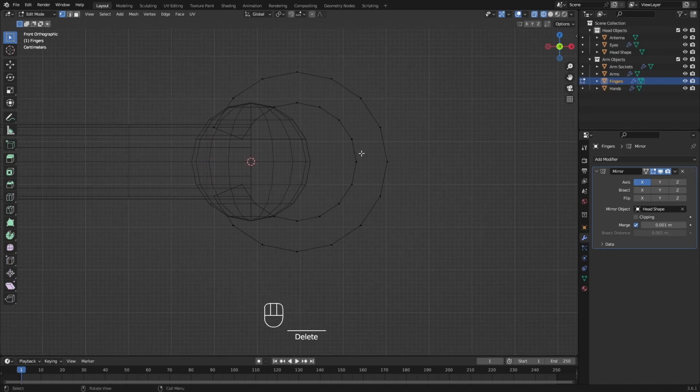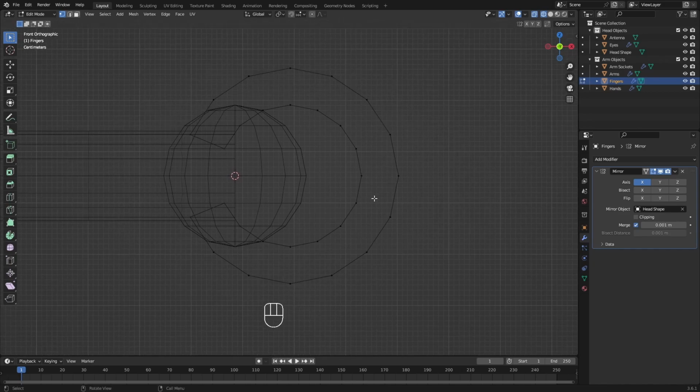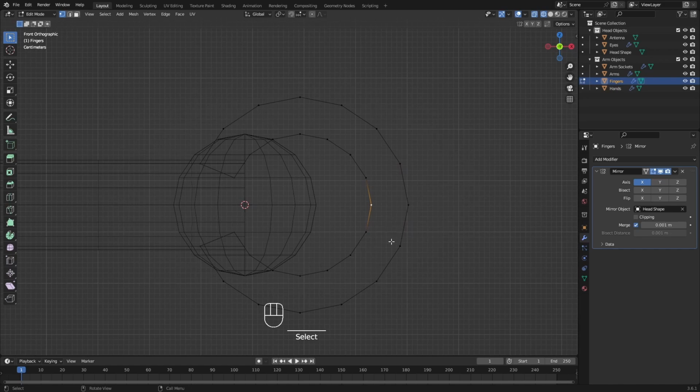Okay, here I'm going to do something first, because since there are two fingers, and we want this upper half to be a finger and this lower half to be another one, we are going to need to separate these two guys here. And to do that, we are going to press the letter V. So press the letter V, and then we separate one from another. And right click to make it be on the same place. Select this other one, V, and then we separate it.